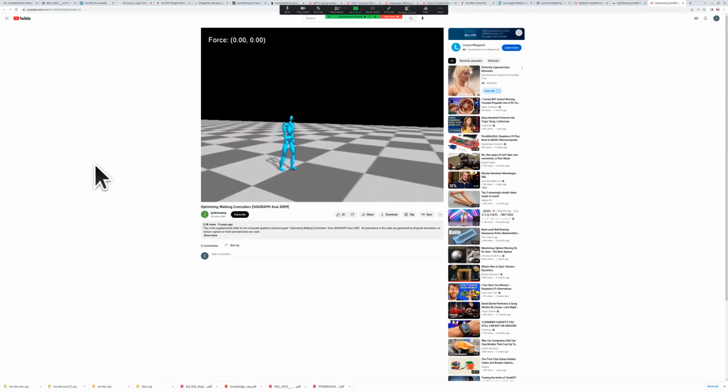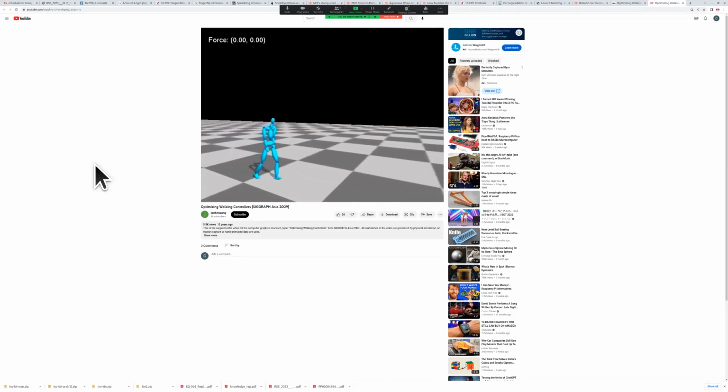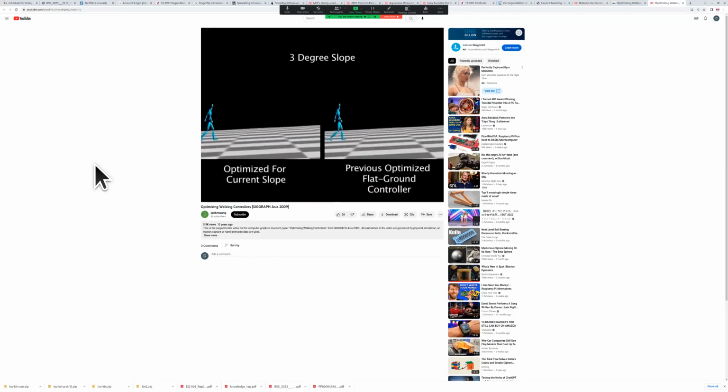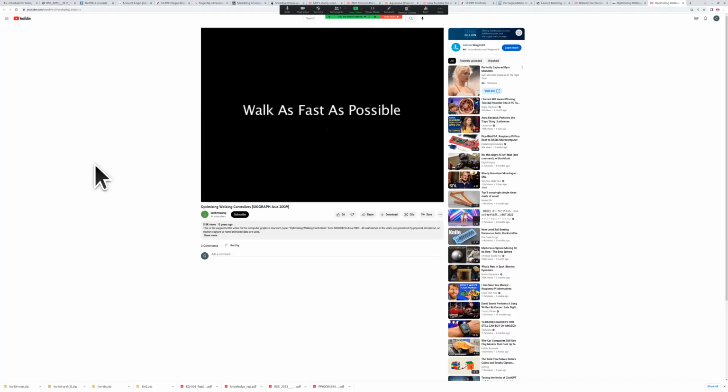And a question I'm going to ask at the end of the video is, if you live in a world where you get randomly pushed, what's the difference between the controller the optimizer is going to come up with in this situation versus the one it comes up with if you live in a world where nobody pushes you around? Here, we're climbing a slope, and the thing they generated for the flat surface didn't work, so they had to re-optimize for slopes. So that means you have to select, I'll call them pre-learned behaviors for different situations.